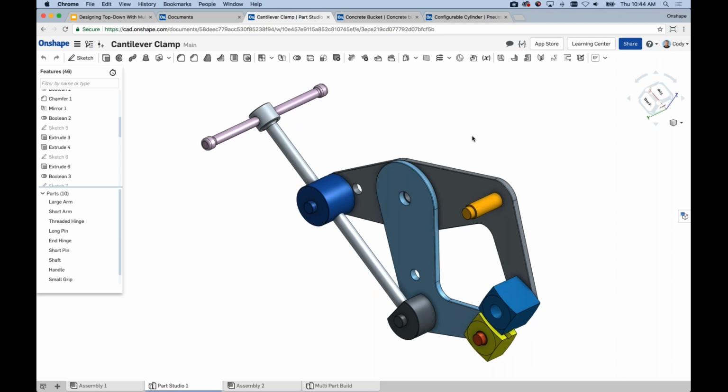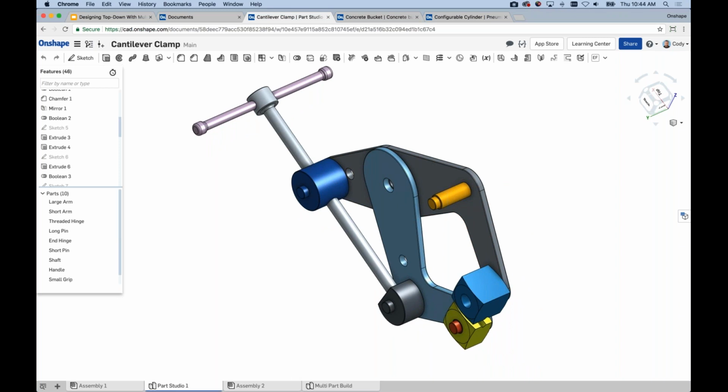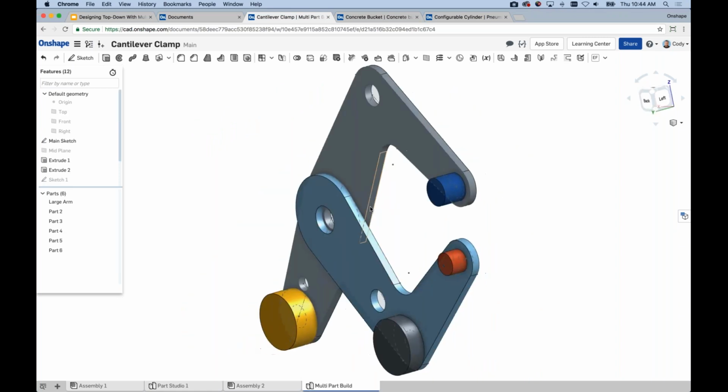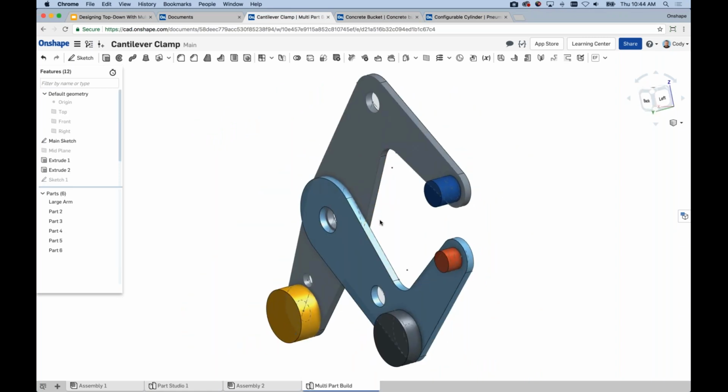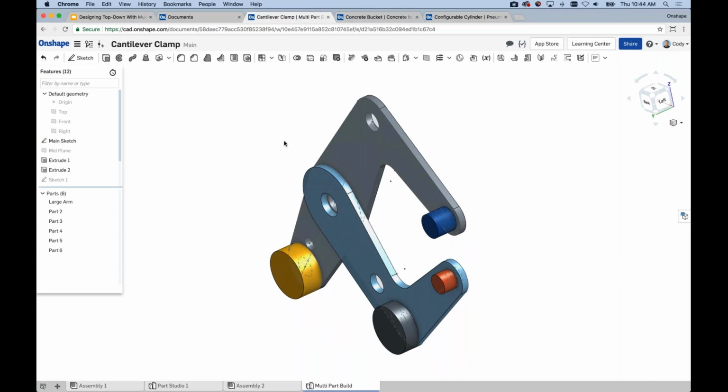The question you would ask yourself in some scenarios is, what do I do if I wanted to make a design change? How do I push all of those design changes up through the assembly and so on? And this is where Onshape really shines, because we don't have that intermediate step. If you change a Part Studio, it's going to, of course, update all the parts in the Part Studio, but it'll also automatically update anywhere that was inserted in that document. So there is no need to re-export everything again and re-import anything again into the assembly, or update individual parts. I don't have to worry about any of that stuff because the Part Studio went directly into the assembly. It will update directly as soon as designs change.